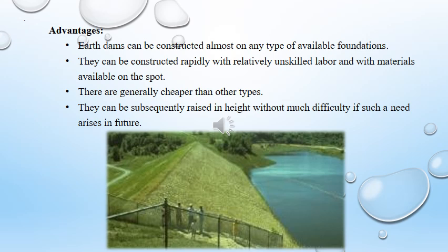The advantages of earth and rock fill dams: earth dams can be constructed almost on any type of available foundation, and they can be constructed rapidly with relatively unskilled labor and with material available on the spot. They are generally cheaper than other types, and they can subsequently be raised in height without much difficulty if such a need arises in future.